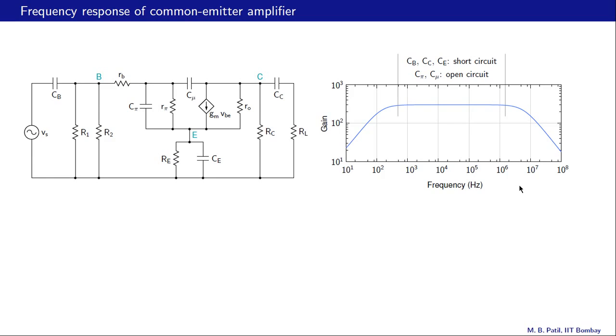Now, where does the frequency dependence come from? It's easy to see. Let's take a resistor. The relationship for a resistor is V equal to I times R, and there is no omega in the relationship. So the frequency dependence surely cannot come from resistors. Similarly, this voltage controlled current source does not have any omega in its relationship.